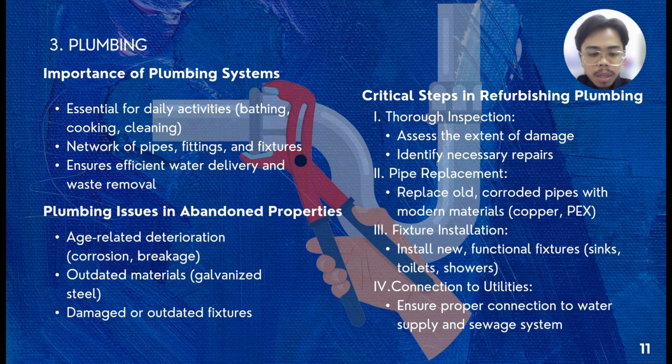Plumbing plays an important role in our daily life by providing clean water and removing waste, though we often overlook its importance. In abandoned properties, the plumbing system can become damaged due to age, outdated materials like galvanized steel, or broken fixtures. Refurbishment should begin with a detailed inspection to identify problems and necessary repairs.